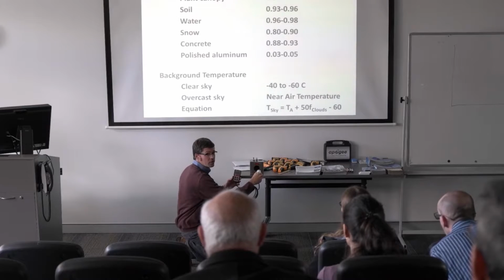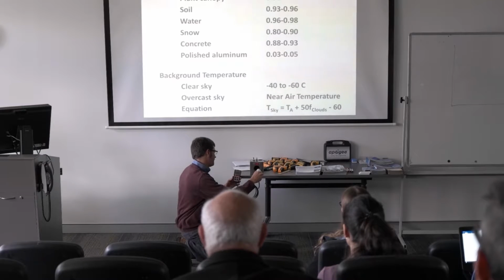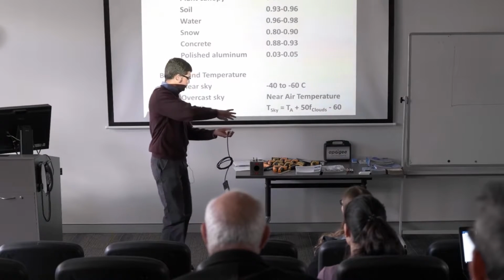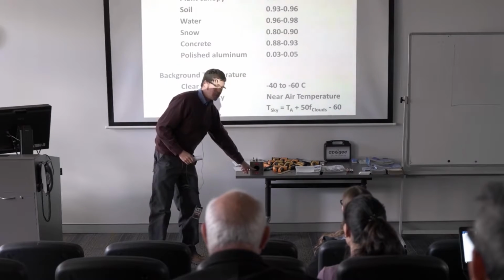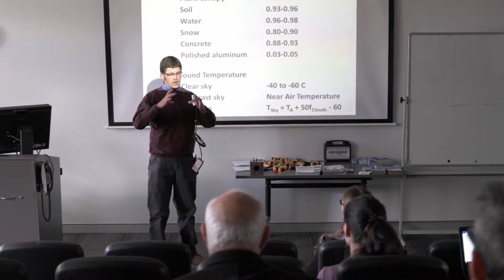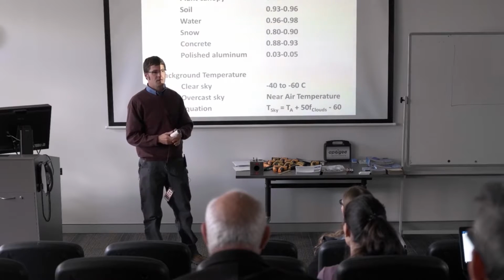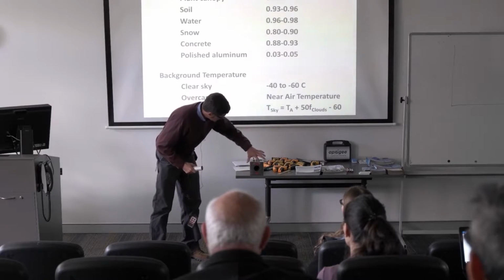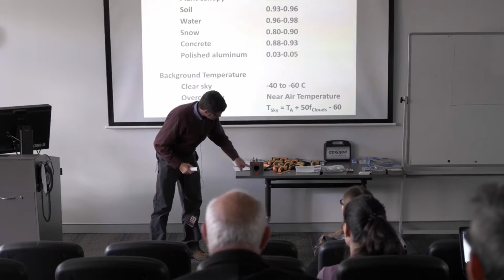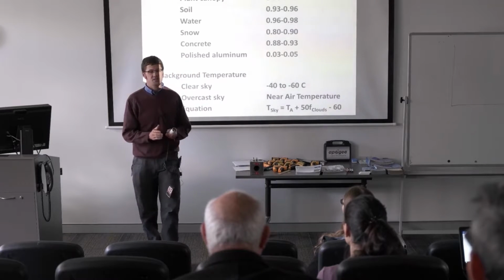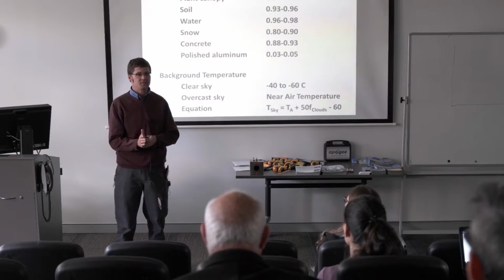Yeah, it's getting colder and colder. So now we're about probably 12 centimeters, maybe 14 centimeters away, and we're reading 30 instead of 38. And so what's happening is we're moving it further and further from the black body. We're seeing more and more within the footprint that this thing measures. And so now we're starting to move it away, and we're seeing the sides where it's polished aluminum in addition to the black body. And that's determined by the field of view of the sensor.